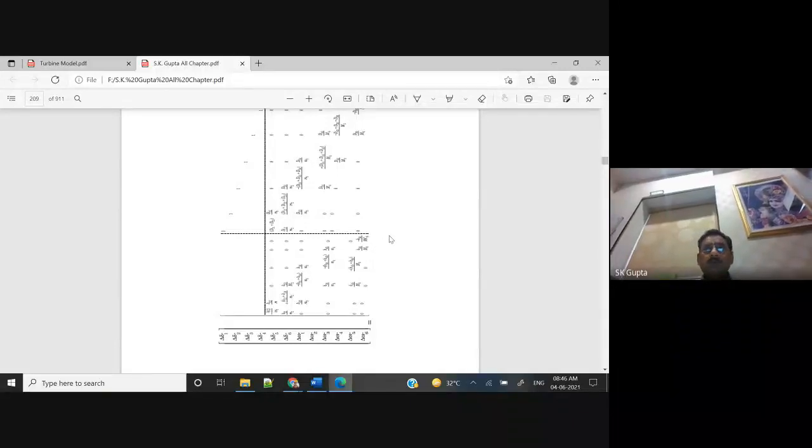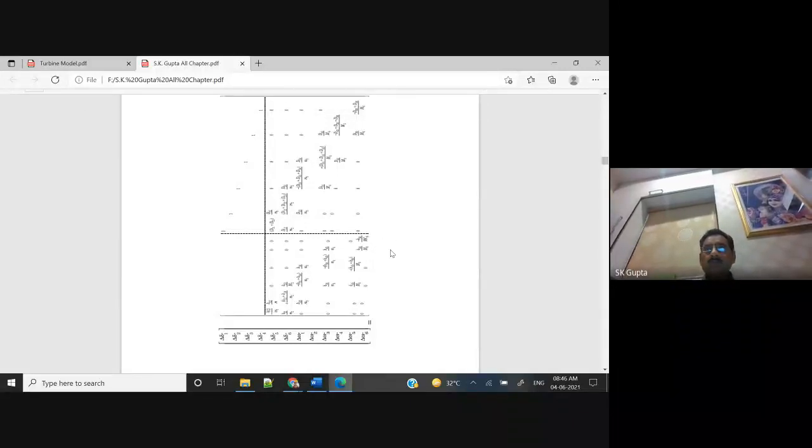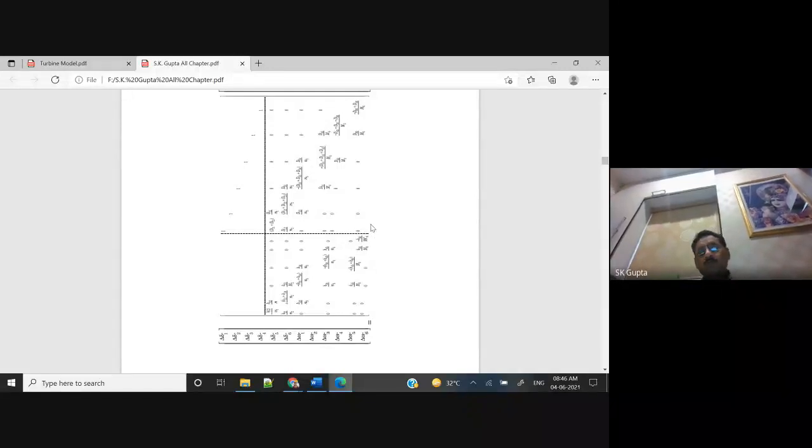जैसे टर्बाइन हमारा शाफ्ट के थ्रू किससे कनेक्टेड है, रोटर से. रोटर मैग्नेटिक कपलिंग के थ्रू किससे कनेक्टेड है, स्टेटर साइड से. और स्टेटर इलेक्ट्रिकली किससे कनेक्टेड है, ट्रांसमिशन साइड से. और ट्रांसमिशन साइड पे हमारे डिफरेंट डिवाइसेस भी कनेक्ट हो सकते हैं, जैसे शंट कंपनसेशन, शंट कैपेसिटर, सीरीज कैपेसिटर भी कनेक्टेड. So because of everything there can be different modes of oscillations.